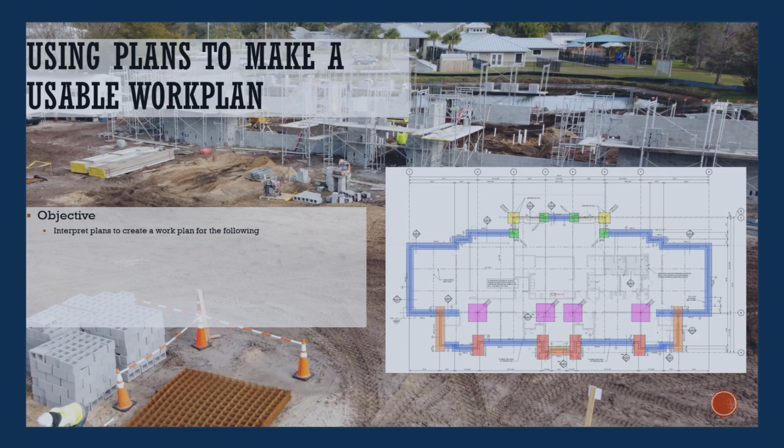You may be wondering what a work plan is. Well, a work plan is what you make it. Personally, I have found that putting all the information on an extra plan sheet works best. The sheet can be used to help identify certain elements like you see here with the footings, but it can be much more. We can also have areas marked up for staging, concrete quantity calculations, and whatever else helps communicate the plan to the team.